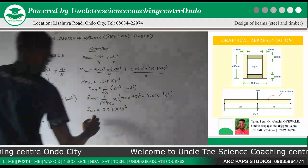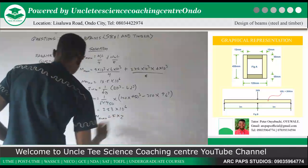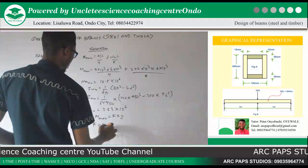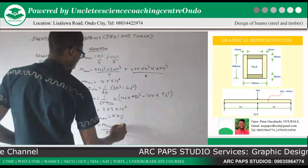Now our Mmax is given by our bending stress times our sectional modulus, which is F times Z mathematically. So it means that our F will give us Mmax divided by Z if you make F the subject of the formula.